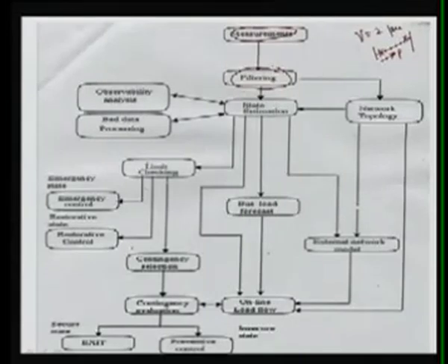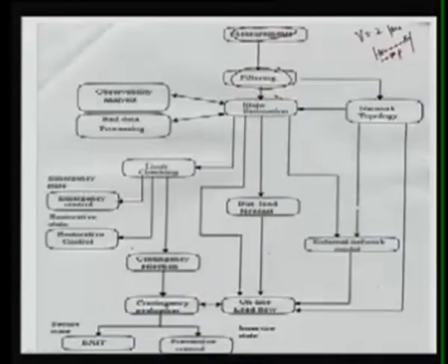Still we have some errors in the measurement due to the communication links, due to the measurement units themselves, due to your CTs and PTs, and those errors we have to minimize in the state estimation function.